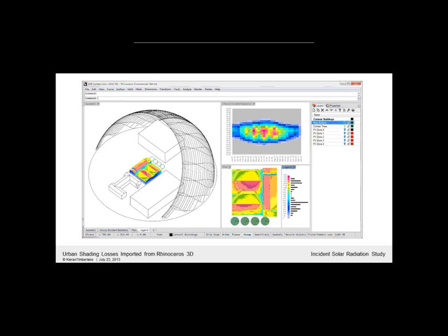We initially developed this tool to build a qualitative understanding of the relationship between solar heat gain and the building envelope. So the lower right image might help us identify places where we wouldn't want to place glazing if we were in a cooling-dominated climate, while the upper right image might help us identify whether a seasonally selective shading device is providing adequate shading in the summer and adequate light penetration in the winter. Next slide, please.